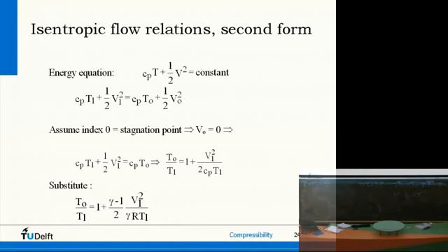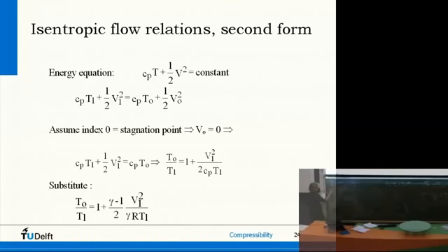Yeah? Step 1. We need to work our way to CP. What we'll do now is divide by CP. R divided by CP is equal to 1 minus CV over CP. Is equal to 1 minus 1 over gamma, actually. CP divided by CV is gamma. Multiplying by gamma, so we get then gamma minus 1 over gamma.